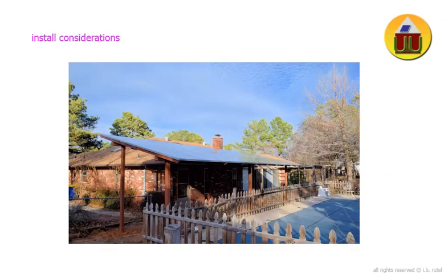Once you have determined the type of solar system and the size and number of panels, you now need to consider where to place them. Generally, you want to place the panels in a south-facing direction in the northern hemisphere and a north-facing direction in the southern hemisphere so that you are most directly facing your panels towards the sun. There's also a consideration of the actual angle. This is best determined by modeling software with the installation company, since your local environment can affect the efficiency and total light you can collect.